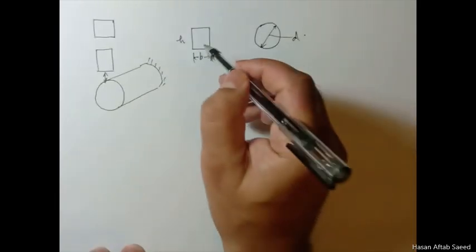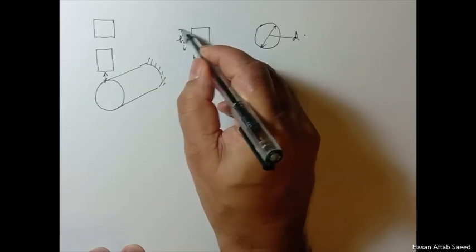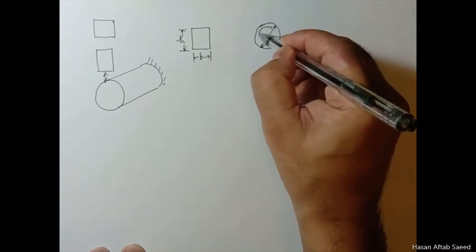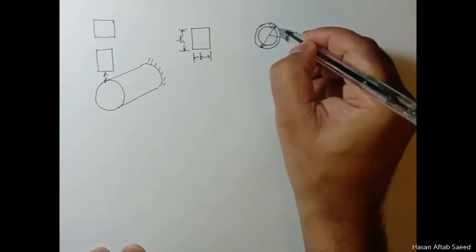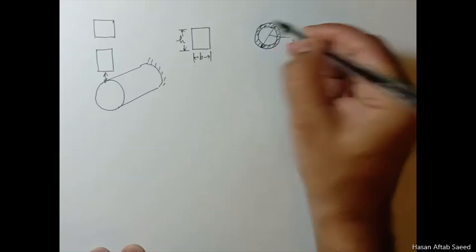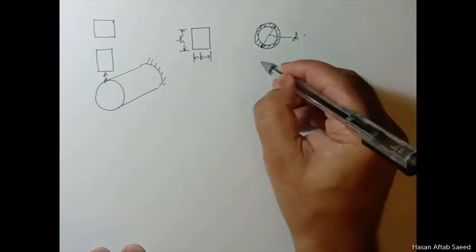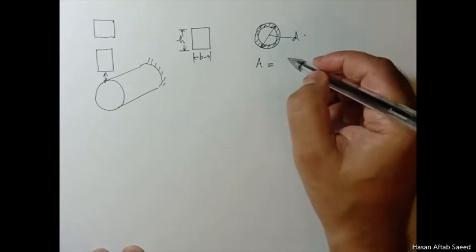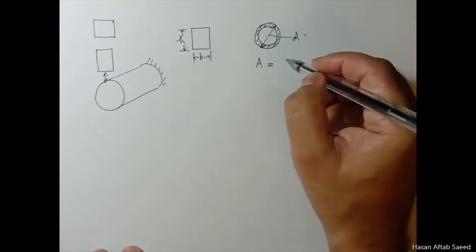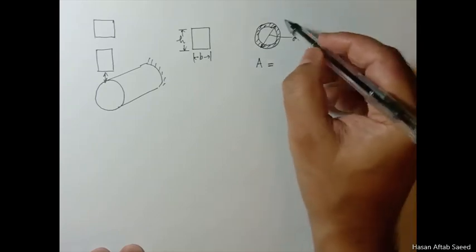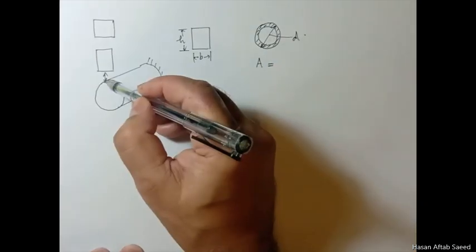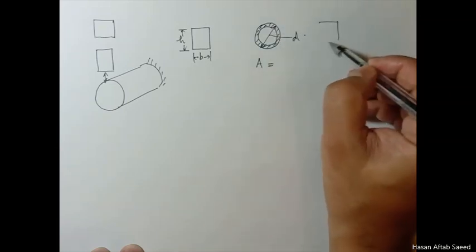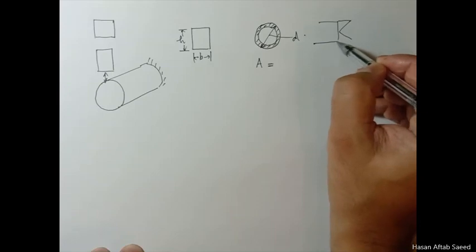Now the practice is that we calculate the area of this rotating beam test specimen that bears more than 95% of the maximum stress. And that is because we know that the stress distribution here for bending is something like this. If this is the stress distribution.